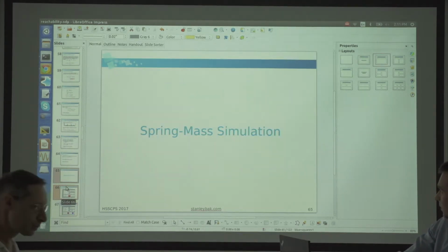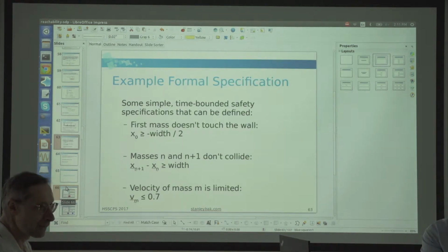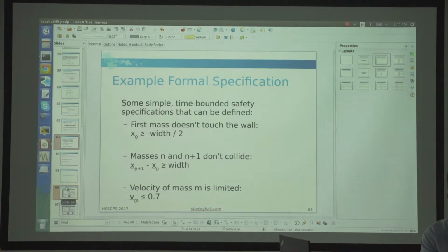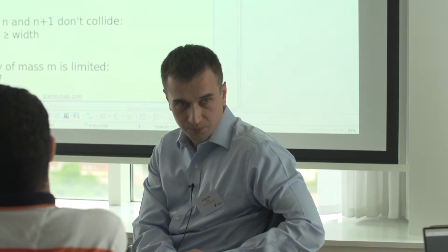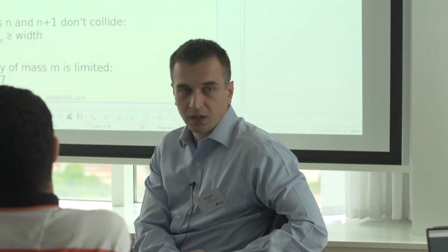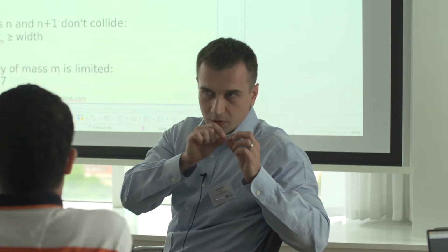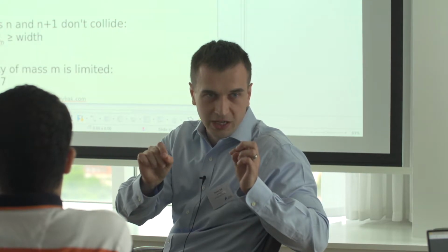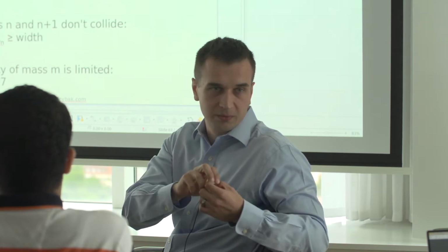So I have a question. So here you have no inputs in the system. Yes. But I didn't know if you want to prove things. You assume that on each sampling time the input is constant. So you will lose some trajectory. So how do you manage when the input is moving? So the typical way it's handled is you compute the set when the inputs are fixed, and then you reason about when the inputs change, how far can they change from any of the fixed inputs, and then you'll bloat the set based on that.